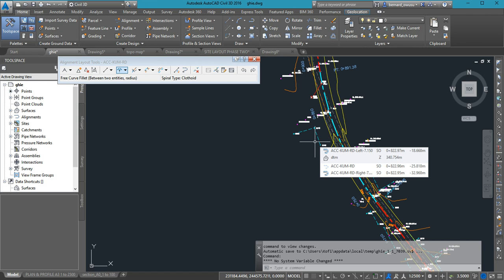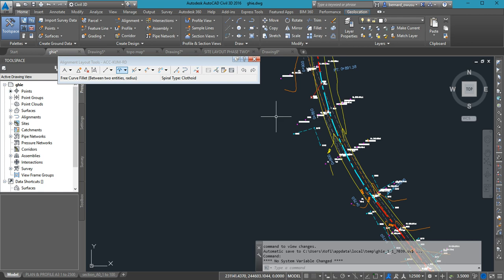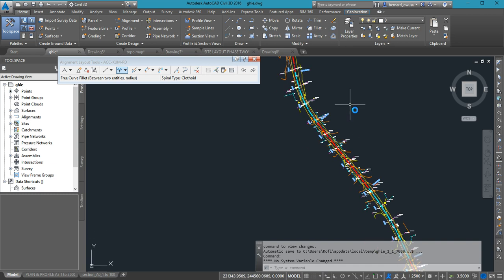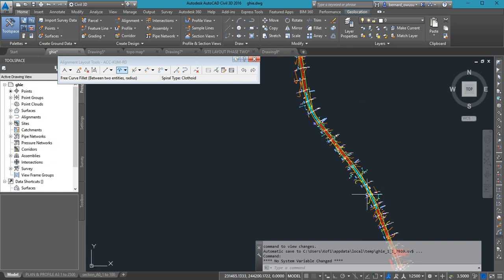So please, can we continue? With practice, you become perfect. Now, some of you had challenges. Why? Because if the tangent is too short, it will not be able to insert the curve, because by inserting the curve, it will take part of the tangent. Are you okay? So that's why if you look at what I did now, I'm here, but some of you are still around somewhere here.